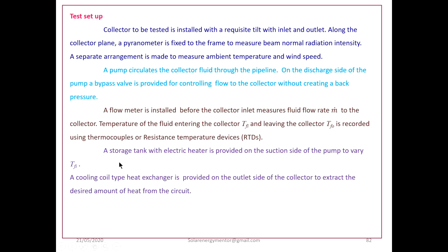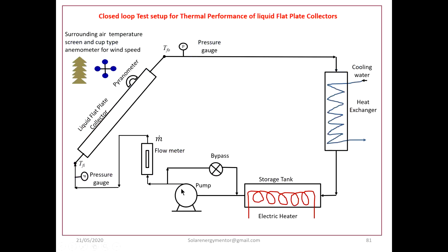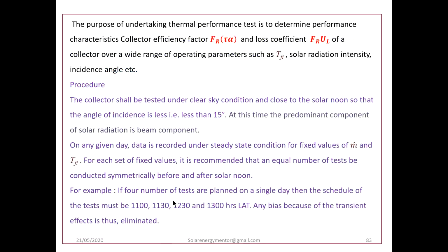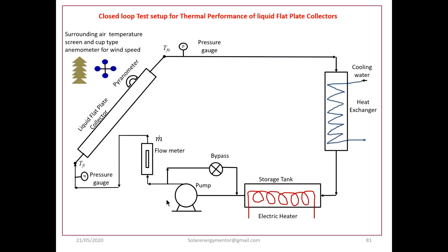Okay, so a storage tank with electric heater is provided on the suction side of the pump. So on the suction side of the pump, storage tank and electric heater are provided. A cooling coil is provided here to extract the desired amount of heat from the circuit. Now the purpose of undertaking the thermal performance test is to determine the performance characteristics, the collector efficiency factor. Okay, so this setup is as per Indian Standard 12933. This is a thermal performance test.